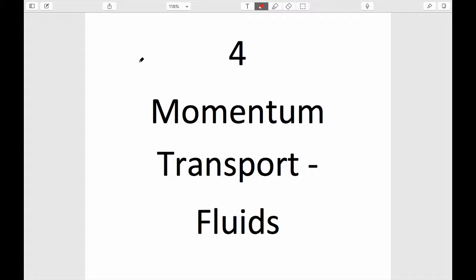You might recall that when we started talking about one-dimensional elements, we could develop the equations for a finite element, a one-dimensional two-node finite element, just by writing Darcy's law along the length of a pipe, and split the partial derivative dh/dx into two parts, one which was the upstream head minus the downstream head, divided by the length over which it occurred, L in our case.